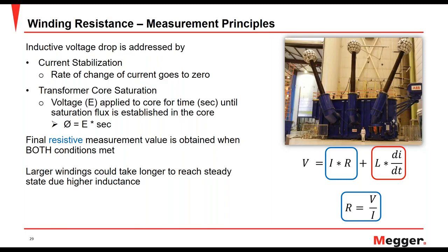Now, it's noteworthy to understand that if you have a large winding, for example a generator step up transformer or transformers of that sort, it could take longer for the reading to stabilize because of the higher inductance of those types of windings.